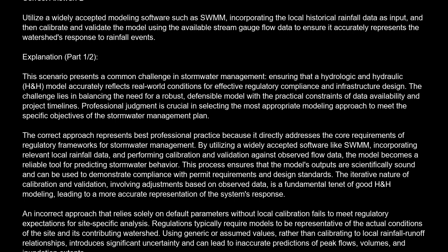An incorrect approach that relies solely on default parameters without local calibration fails to meet regulatory expectations for site-specific analysis. Regulations typically require models to be representative of the actual conditions of the site and its contributing watershed.